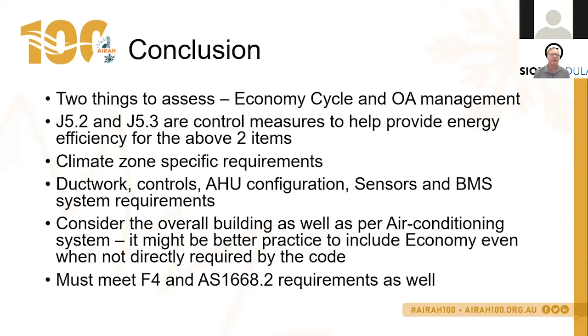Obviously, if you have slightly higher internal temperatures, etc., available, then you might be able to use slightly higher enthalpy values. And then if you're controlling to lower or tighter temperatures for the internal conditions, you might need lower enthalpy values. So it does depend on what internal conditions you're trying to control to.